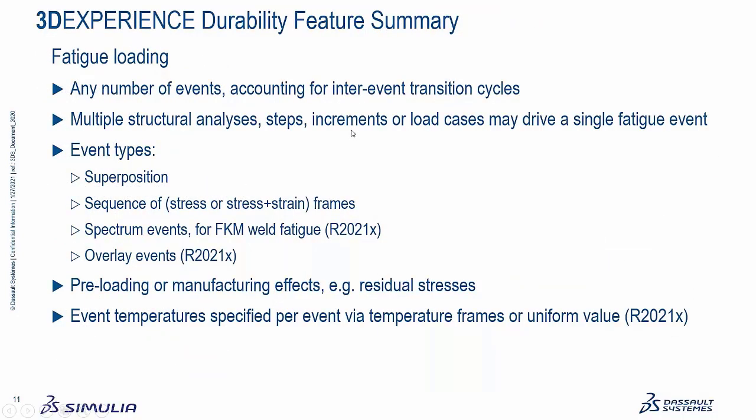As I said, we cover nearly all of the loading capabilities in FE-Safe: the superposition, sequences of frames or datasets, as it's called in FE-Safe. For FKM, we allow you to specify spectrum events directly, and you can overlay events, for example, having higher frequency cycles superimposed on some lower frequency cycles, right?